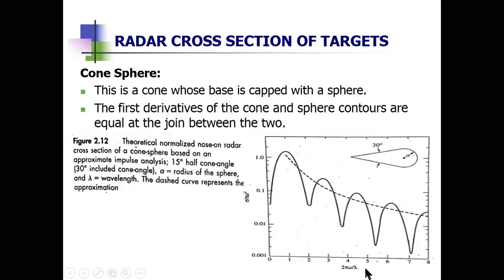Increasing frequency means lesser lambda, right? If this is becoming lesser, this becomes larger. That is, 2 pi by lambda becomes larger. So because of these things, this cross section will no longer decrease with increasing frequency. So we have a graph like this, but it will level off and even decrease at higher frequencies. Higher frequencies means lower lambda, and lower lambda means this expression is higher. That's why it is decreasing at higher frequencies, where other factors dominate. That's why we have such a graph.